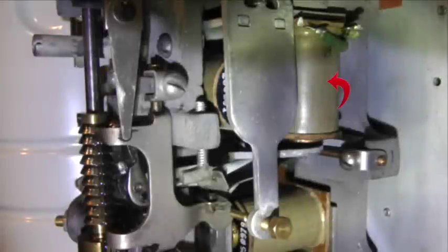This is the right side vertical magnet. Its twin is adjacent to it on the left side. These magnets are energized and de-energized repeatedly during the pulsing of the tens digit to enable the vertical stepping function to occur. This is the vertical armature. It operates and releases repeatedly during the pulsing of the tens digit in concert with the energizing and de-energizing of the vertical magnets.